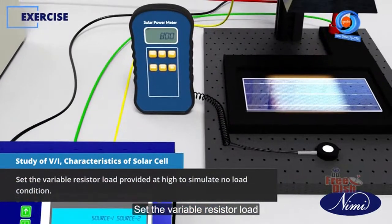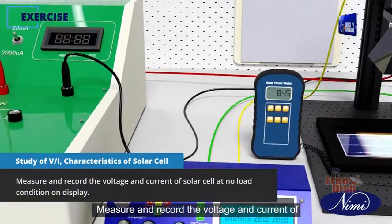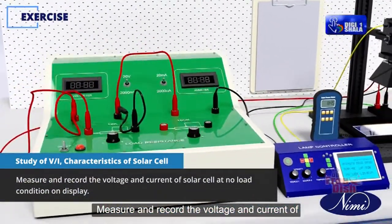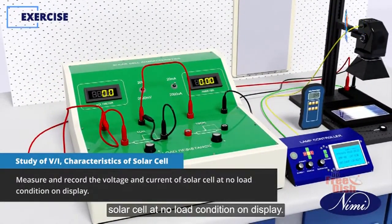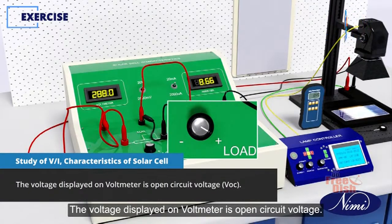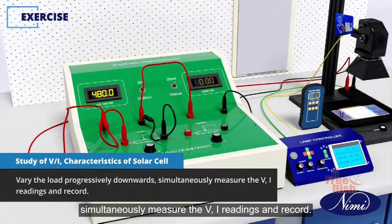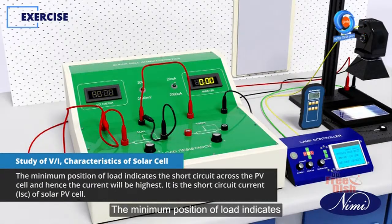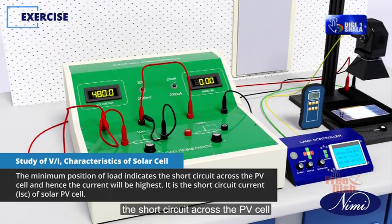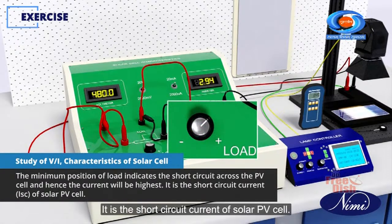Set the variable resistor load provided at high to simulate no load condition. Measure and record the voltage and current of the solar cell at no load condition on display. The voltage displayed on the voltmeter is the open circuit voltage. Vary the load progressively downwards. Simultaneously measure the VI readings and record. The minimum position of load indicates the short circuit across the PV cell and hence the current will be highest. It is the short circuit current of the solar PV cell.